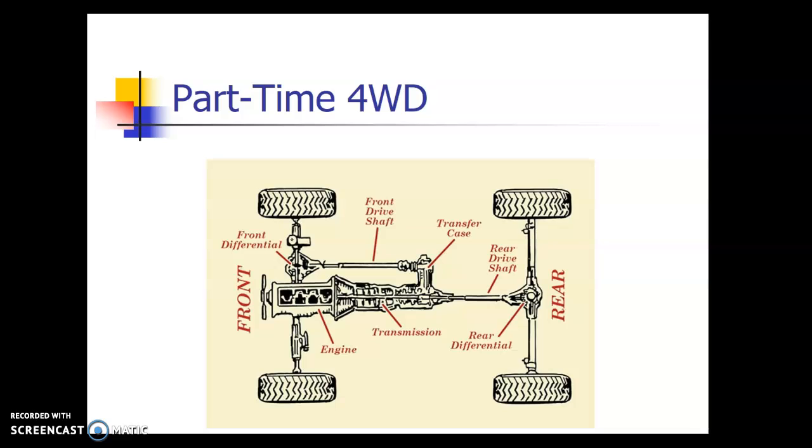So again, think old-school American Jeep trucks, etc. You have power coming right here from this engine to the transmission. This is the transfer case right here, where that power is going to split out and either go straight through for two-wheel drive, or when you select four-wheel drive, it's going to come out of the transfer case to the side, and then go down to the front differential, which works the same as the rear differential, but in the front, hence the name.